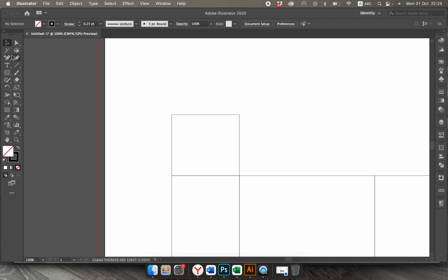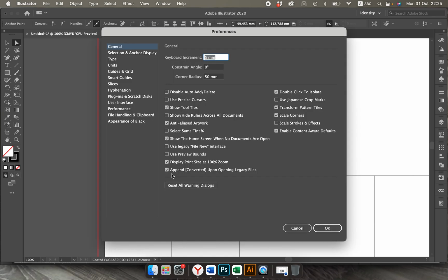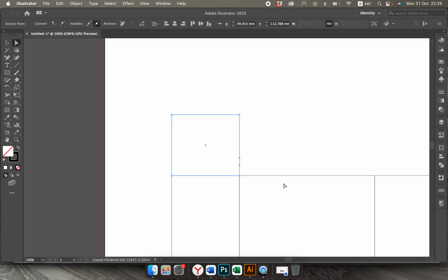To make a locker, I will use the plus pen tool again. From the left side, I will create one joint, and from the right side, two joints. Now, just like I did for the glued bottom, I will move this element into the corner and then set the same step, about 3 millimeters, or in this case it's better to set the cursor step to 1 millimeter.